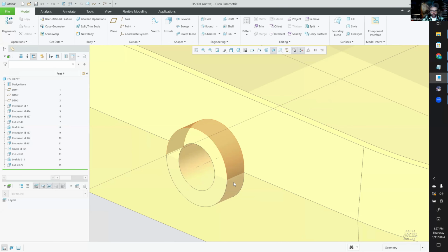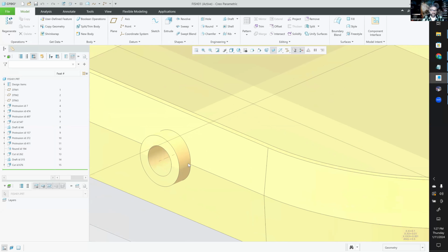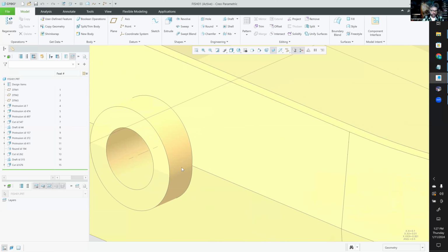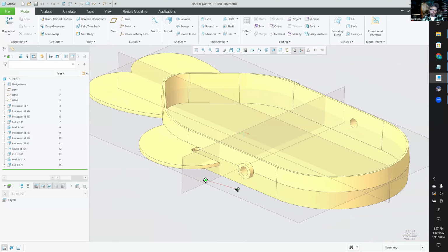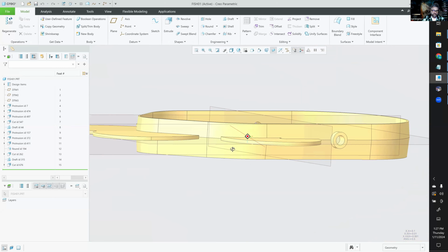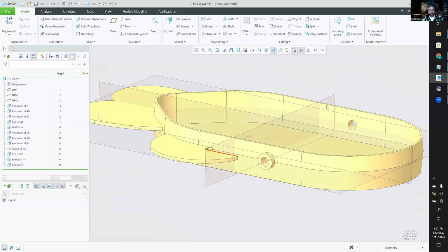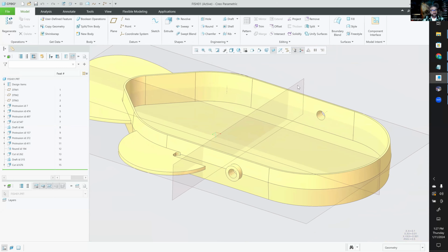But I'm not using the split draft in the eyelet sense on this geometry. So if there's no texture on the part, the mold's going to pull apart and you're probably not going to see the scrape mark. And you could probably get away with no draft right in this 1 millimeter section. Not ideal, but the Chinese mold shop probably wouldn't even point it out.